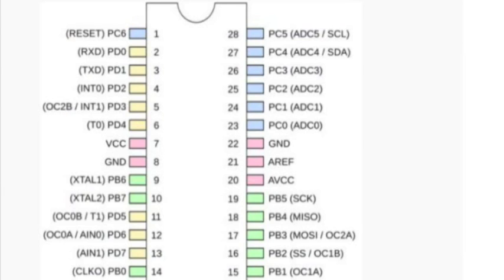There's some overlap, like I mentioned, with the ADC pins and the I2C pins in the upper right-hand corner. All of the hardware PWM pins are labeled OC something something, where the first number is the timer number.